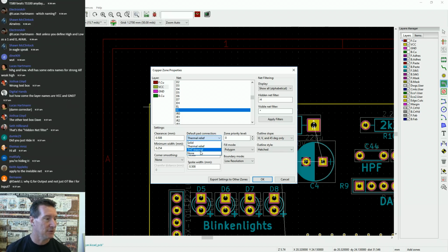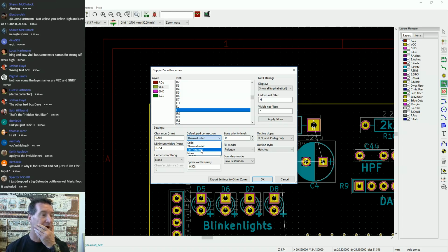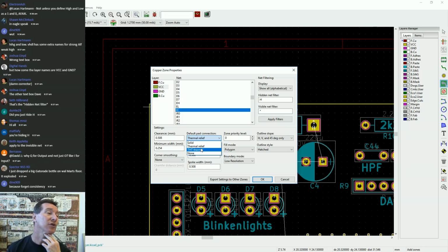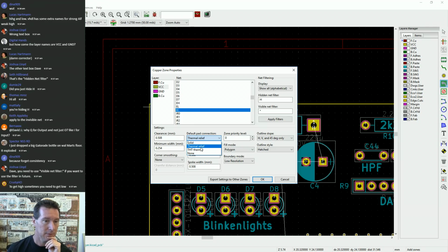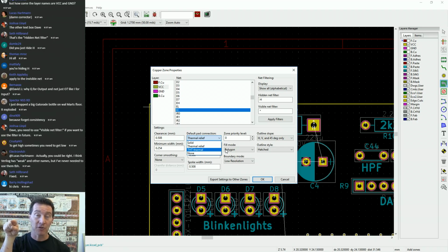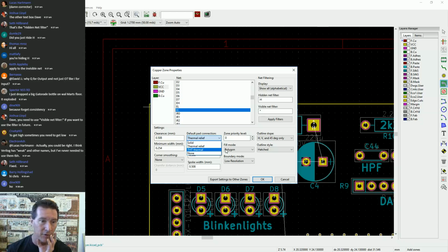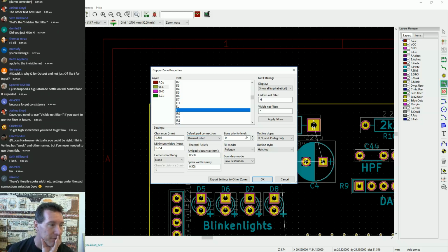I wonder if you can set those up. I wonder if you can actually define. Are they fixed in KiCad, or can you go in and have a user-defined pad connection? I'd like to know that. Like I assume that you can set the diameter or the width of the traces, whether you want 2 connections for your thermal relief that goes horizontal or vertical, or whether or not you want to cross, or whether you want diagonal, or however you want to. Yeah. So anyway, thermal relief.